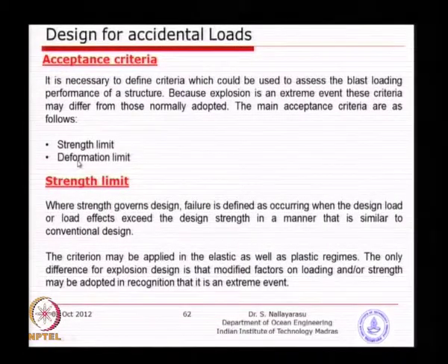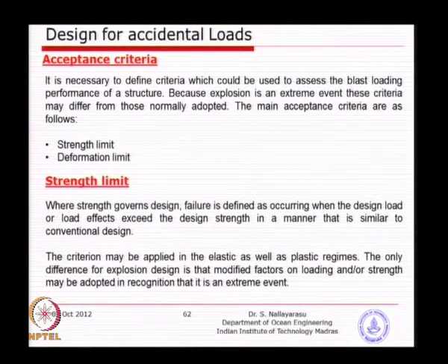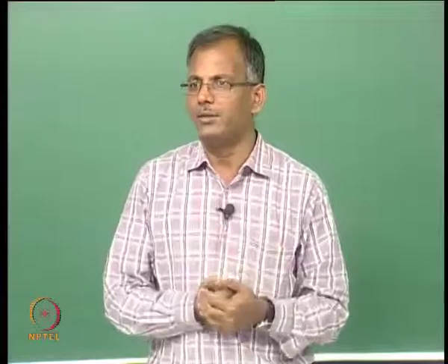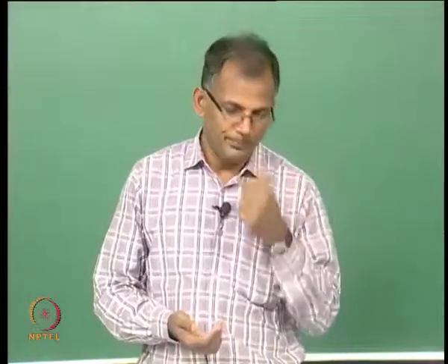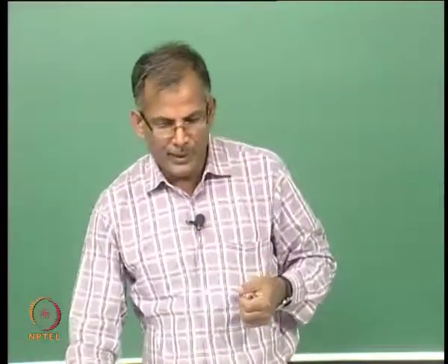How you obtain the deformation is the most important: whether you do a simple static analysis, a second order nonlinear deformation analysis, or a quasi static analysis with a load factor multiplied. Strength limit, again a similar idea to what we discussed about temperature. Similarly, you can do a static analysis multiplied by the dynamic amplification, or you can do a nonlinear analysis.